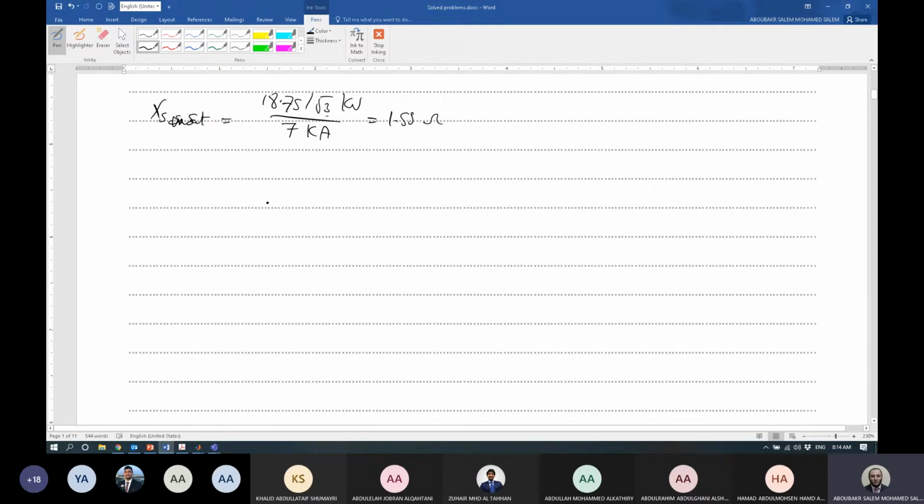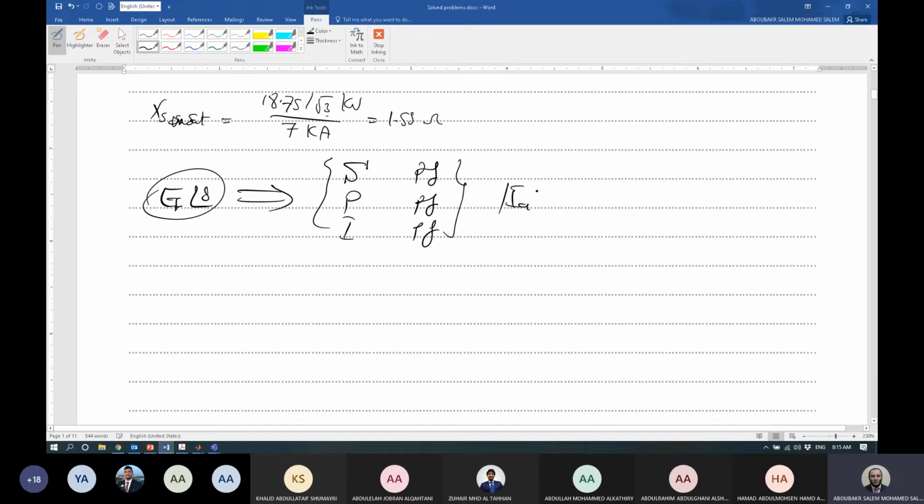So again, in order to get EF at angle delta, we need the loading condition. S is used to get the current, and power factor to get the angle of current, or P and power factor, or I and power factor, and all should be used to get finally IA as a magnitude at angle plus or minus cosine inverse power factor.